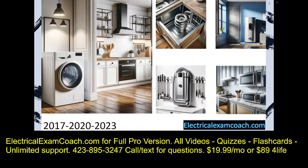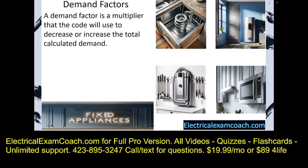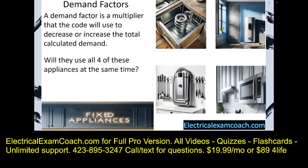Let's get to it. Before we dive into the calculations, let's learn about demand factors. We're going to be using them for the rest of the program. A demand factor is a multiplier that the code will use to decrease or increase the total calculated demand. The question is, will they use all 4 of these appliances at the same time? And the answer is no. So the code makers have made it so we can reduce the overall demand. Instead of just counting them watt for watt, they've made some multipliers that allow us to reduce the demand that we calculate. And remember, if we have less amps, we could have a smaller service. If we have smaller service, we could have smaller pipe, smaller wire, and a smaller overall cost of the job.